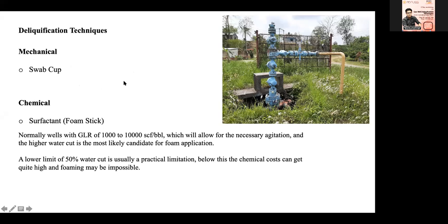And when you are doing the wireline job, basically you are removing your bull plug, and first you will close this crown valve, the swab valve. You will remove your bull plug, and then you will connect your lubricator, the wireline lubricator, above your crown valve. The wireline lubricator has a stripper as well as a BOP, and then you connect that with the reel in the wireline truck.